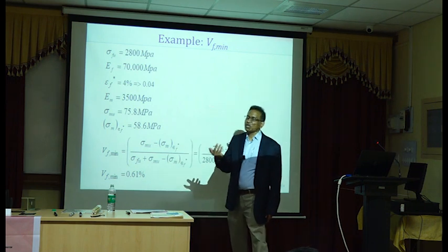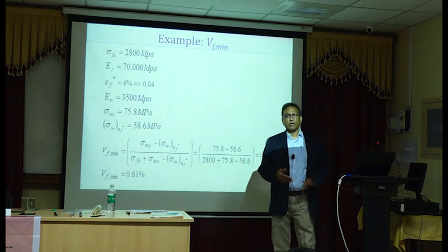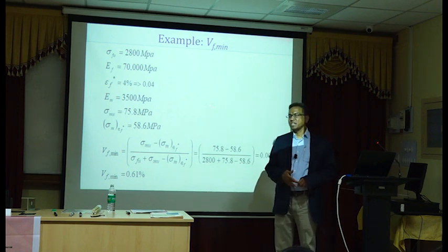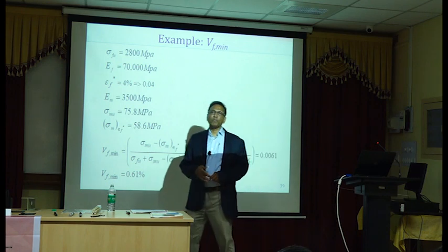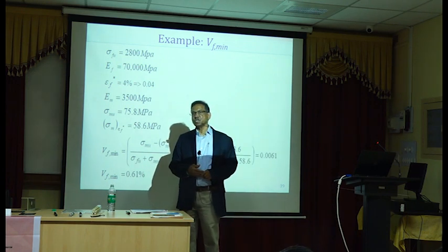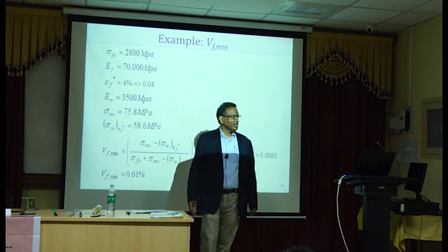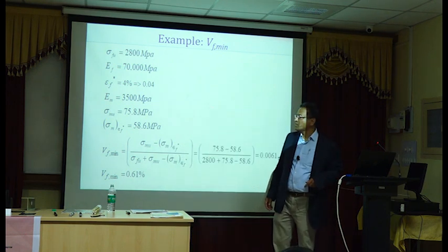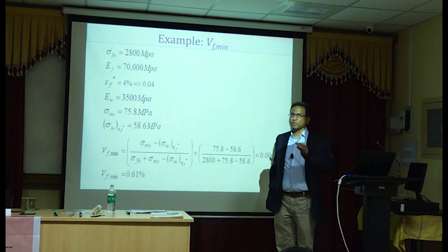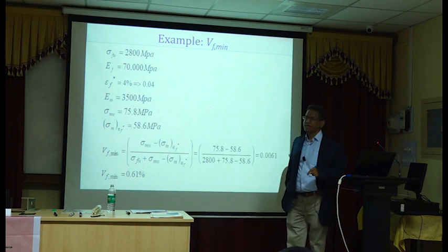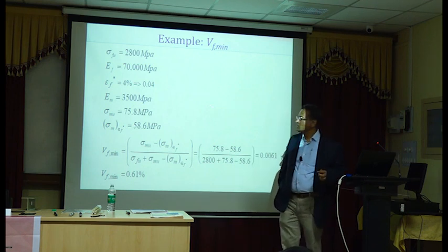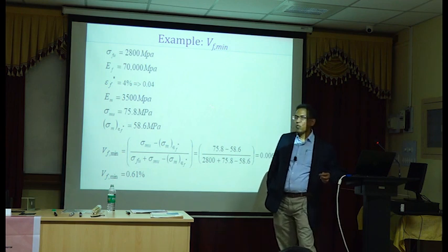What's the percent you normally expect in terms of Vf min or minimum reinforcement? Steel ratio, it will be very, very small. Okay, what about normal steel ratios you use? What percent? 1% is very good, 1% is very practical, 2 is pushing to the limit, but it is possible, 2 is within the maximum limits, depending on your steel, fy and concrete strength. Those things will change a little bit, but 1 to 2% is normal. And what will be the minimum? Minimum is generally about 0.3%.